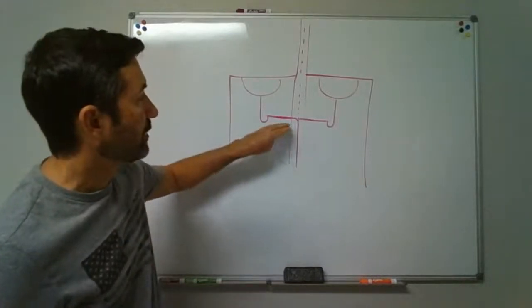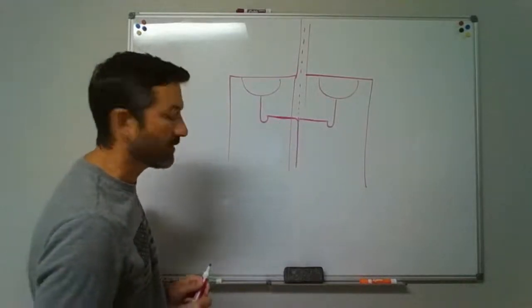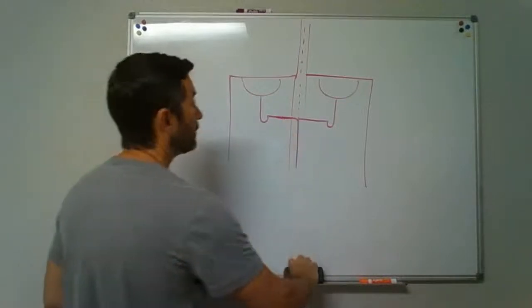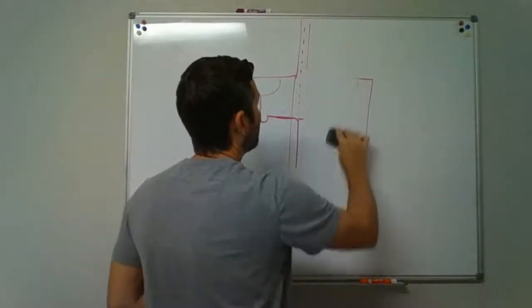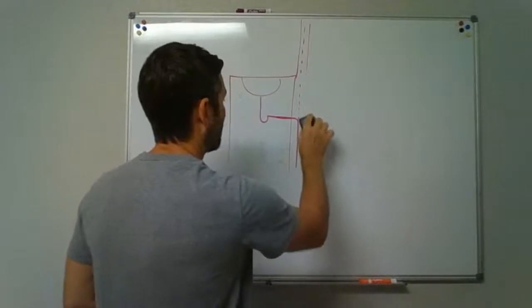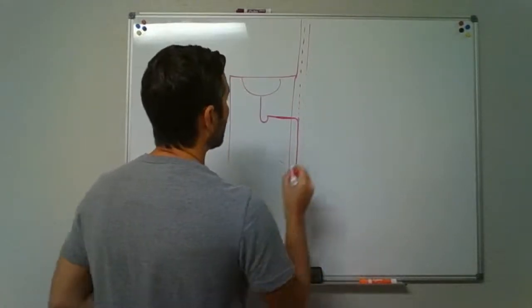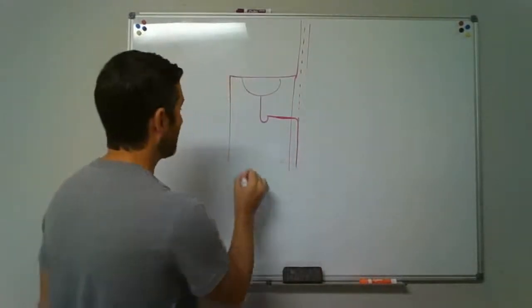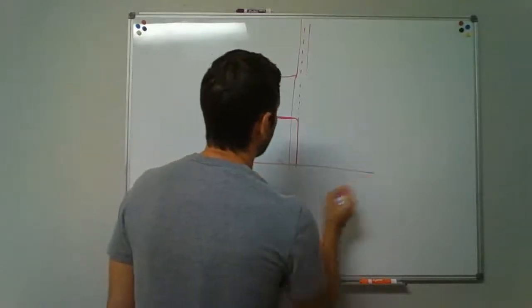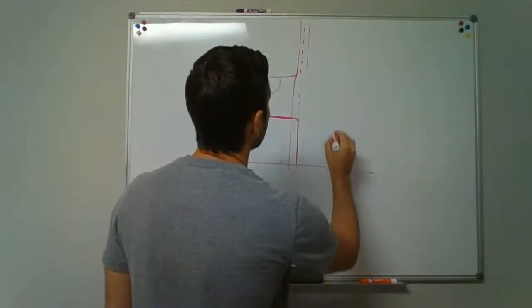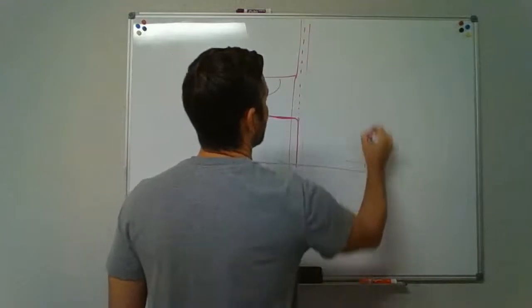Now you could common vent at the same level here. See how they're tying in at the same level? But you could also common vent at different levels. It's the same floor level, but it doesn't have to be at the same level. Let's just say here's the floor, and let's put a shower over here beside it.